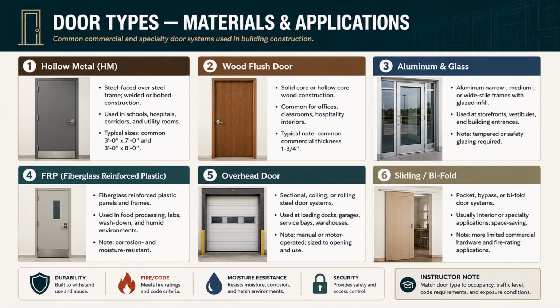Sliding and bifold are pocket, bypass, or bifold door systems, usually interior or specialty applications where you're saving space. Note that they have more limited commercial hardware and fire rating applications, so they're not your go-to where rating or security matters. The icon strip ties it together.